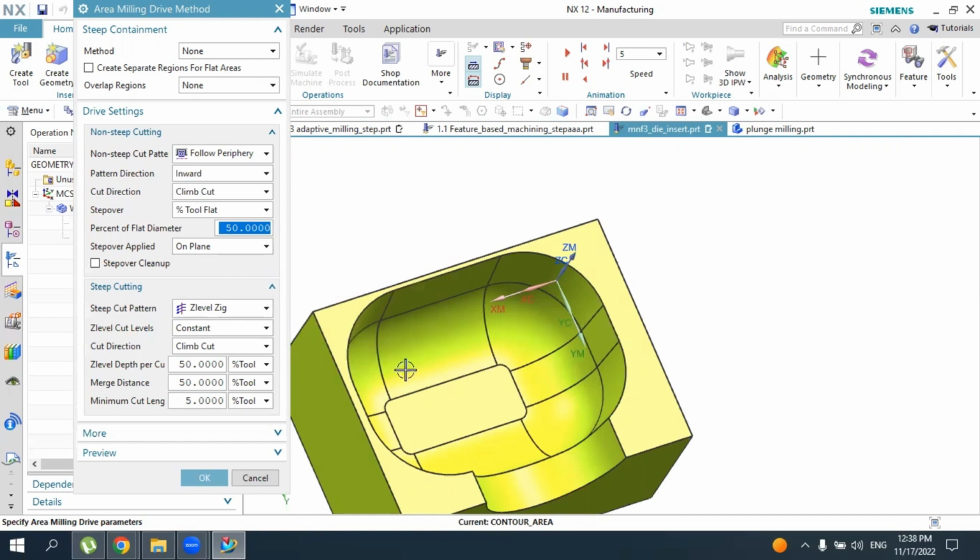That is changing the tool direction. So if you want a smoother surface, it is better to decrease this percentage. So let's make it 30%. We can make it some constant in millimeters or inches, or you can make it a percentage and so on.